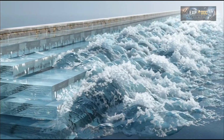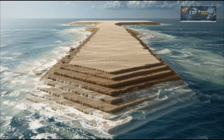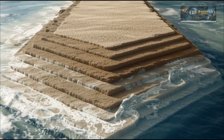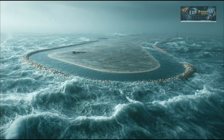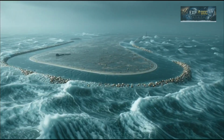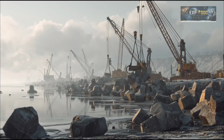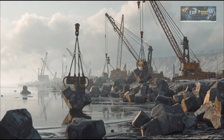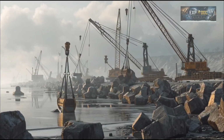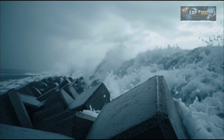However, pumping sand alone is not enough. Once the mixture reaches the site, the water gradually drains back into the sea, leaving the sand behind. Heavy construction equipment then spreads and compacts the material layer by layer. Each layer undergoes strict density testing. If the ground fails to meet the required specifications, compaction continues until the foundation reaches the necessary level of strength and stability.